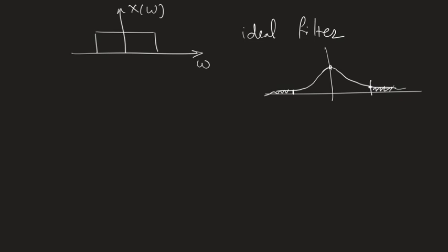And in this case, we can practically say that this is the bandwidth of my signal. So I no longer have to really look for the theoretical highest frequency, because in this case it can go all the way to infinity. I just look at the highest reasonable frequency with some reasonable amplitude. After that, when the amplitude drops, I assume that this does not exist.